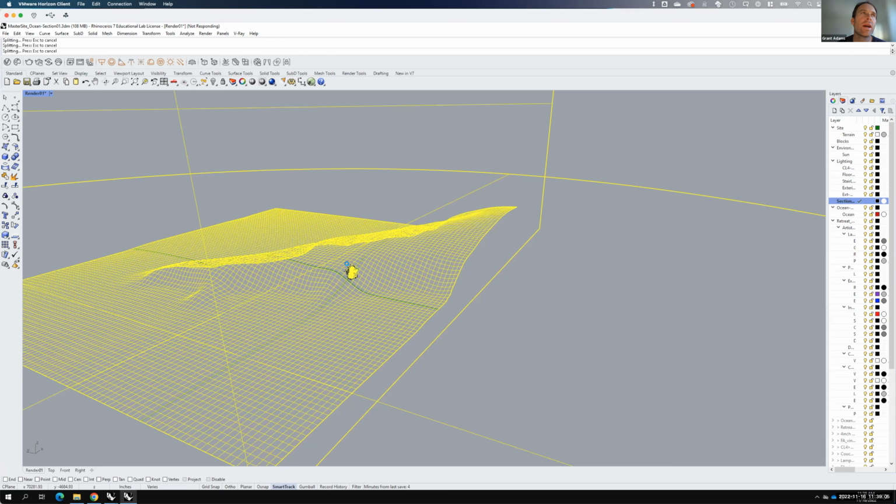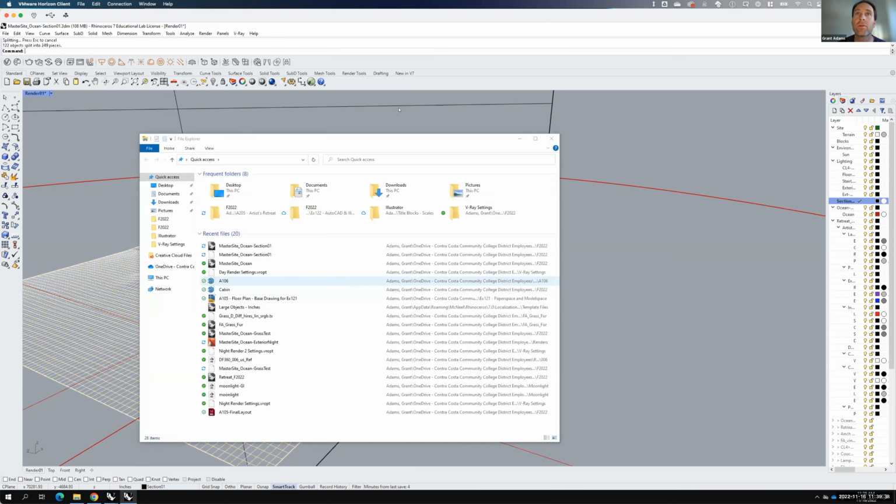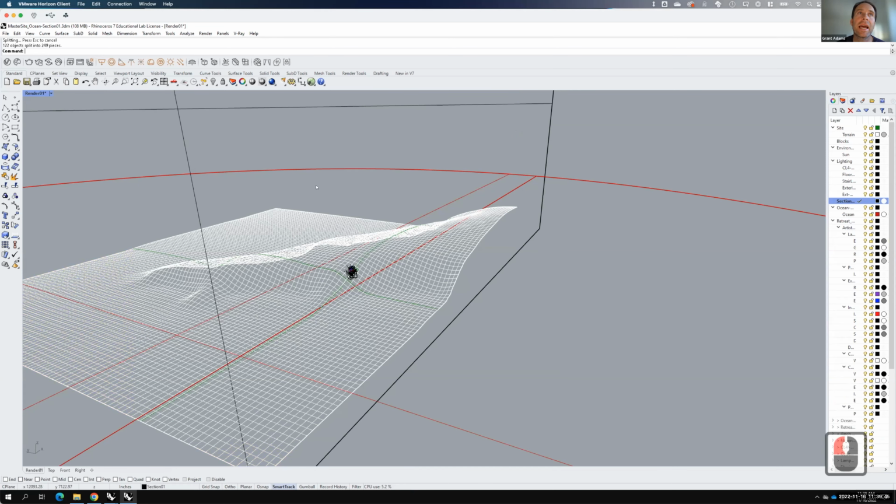Now, I should point out that there are other ways of creating a section. Rhino has a section plane tool, a clipping plane. You can set up a section that way. The problem is it works a lot like SketchUp, where when you do it that way, you'll end up just cutting a hole through your building. So it's great to see temporarily, but we can't study how the light enters your building during the rendering. We're instead left with just a missing half of the building. So the method that I'm teaching right now allows you to preserve the other half of the building. And even though it's not there during the rendering, it will actually render out as if that other half of the building exists. So I like that as a strategy. This is the clipping plane tool right here, and will allow you to create that clipping plane if you want to. I'll demonstrate that a little bit later, but I'd like to get through the actual section cut here first.